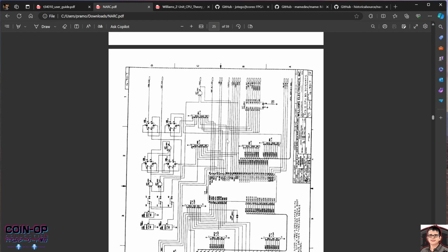But in my first initial stages of research, what I try to do is I try to take a look at the schematic again to enhance my high level understanding of the platform. Right. My goal in the first is to take pictures of the board, find out what the components are. What do these components do? How do they communicate with each other? Now I'm taking a look at the schematic. Okay, all of a sudden it's starting to make more sense. Are there any block diagrams? Is there a high level schematic? How do these components fit on the bus? How do they communicate with each other? So I'm trying to fill in these sorts of gaps about the platform.